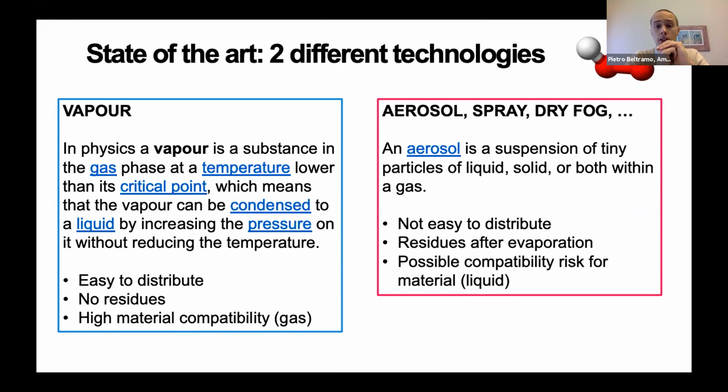This dispersion can be done in different ways. The most common is driven by air, but it could be done through, for example, electrical piezo, which is ultrasonic dispersion. It generates droplets. It can be done through very fast rotation speed. It could be done through compressed air and a small nozzle. All these methods always give you small droplets of liquid within your gas dispersion, okay?